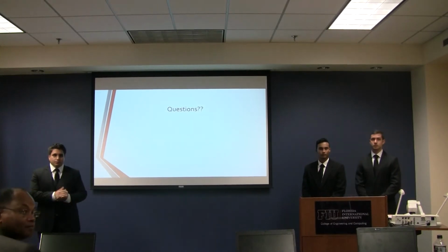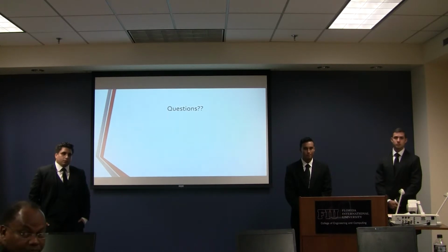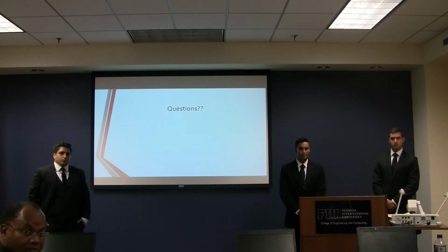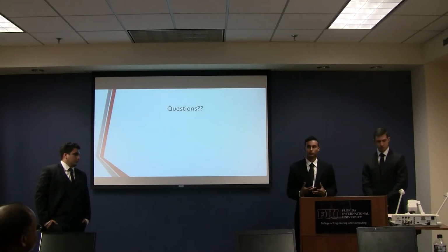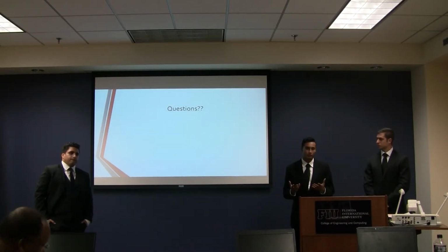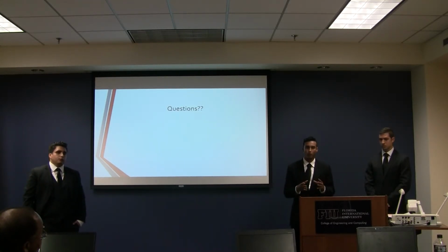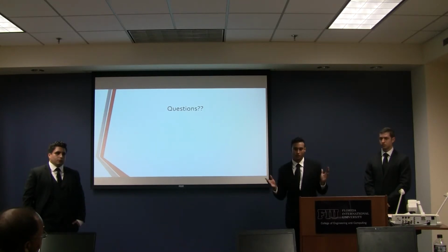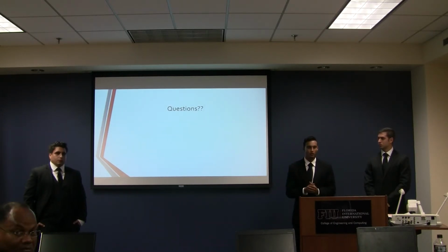I got a question. You guys are going to do some measurement and testing on this, right? Do you have any idea of what your success target is going to be for enhancement of the optimization? Our target is at least a 5% efficiency increase in pressure ratio and increasing our working range. At different RPMs we have different efficiencies, so we want to increase the threshold where our efficiency is at its greatest.